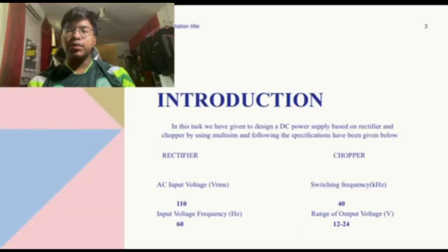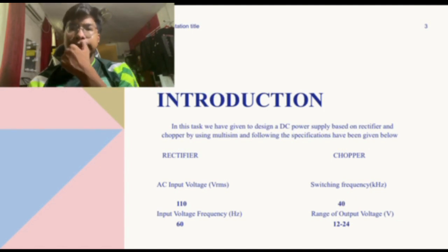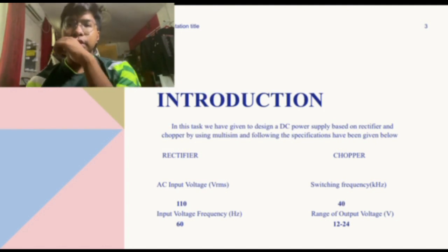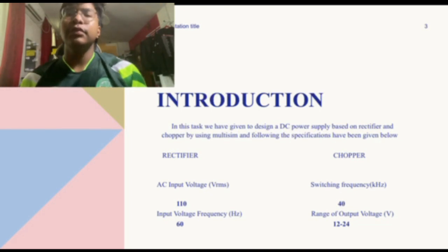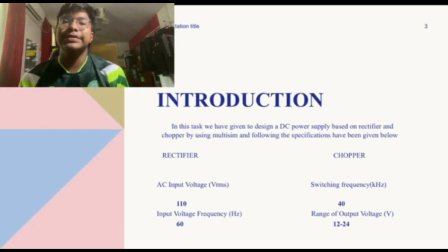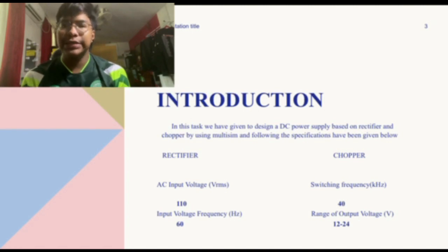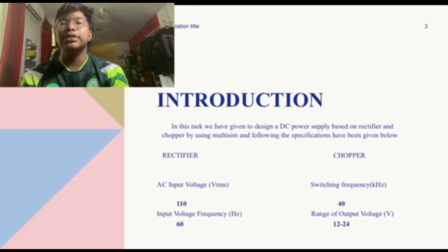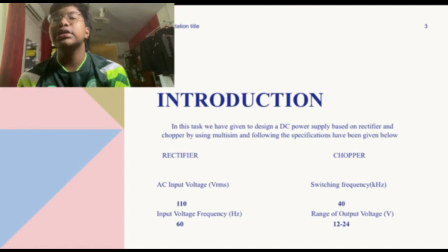In this task, we are given to design a DC power supply based on rectifier and chopper by using Multisim and following the specification that has been given to our group. First of all, for the rectifier, we have to set the AC input voltage VRMS to 110 and the input voltage frequency is 60. For the chopper, the switching frequency is 40 hertz, and the range of output voltage is 12 to 24 volt.